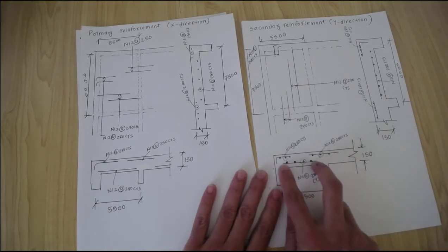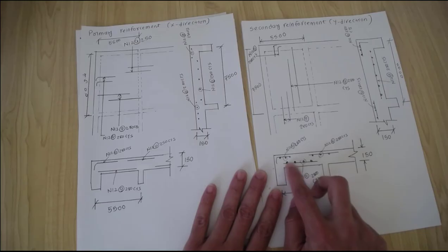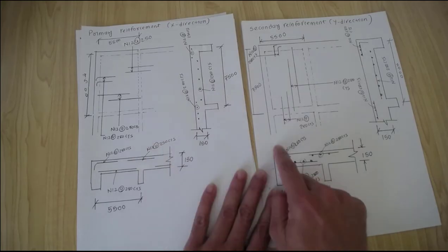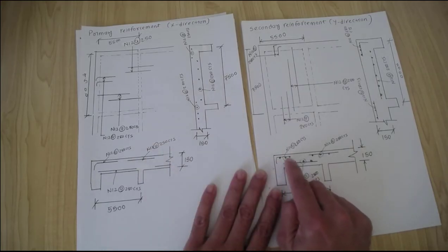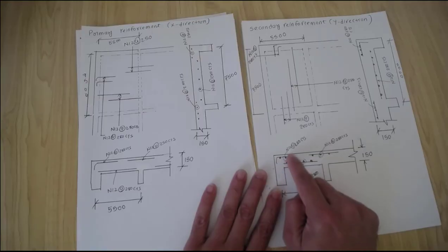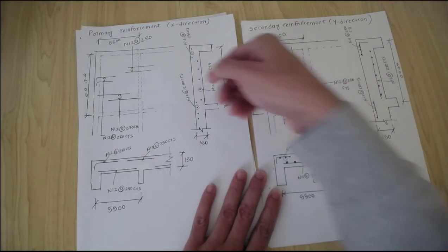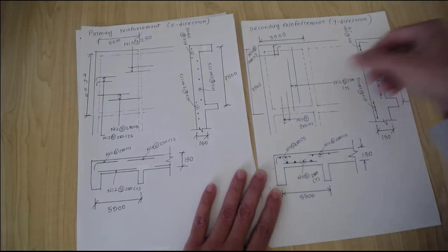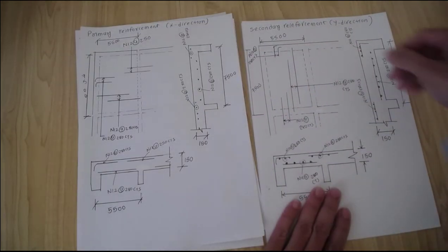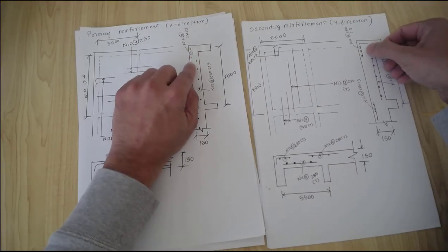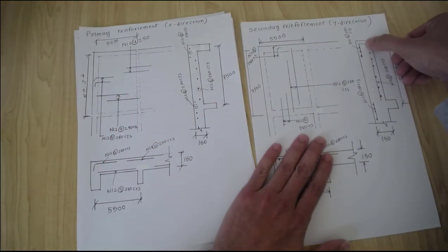Now I can draw exactly the same lines here. I draw those lines, but on top of that we draw the secondary reinforcement shown here. I draw this line and we provide this at this side. So that is secondary reinforcement at 280 center to center distance. I draw this line again and I put those reinforcement here. Similarly here, I draw the primary reinforcement, and then I draw this secondary reinforcement at the midspan. I draw again those primary reinforcement, which are these three dots. I put those three dots, and these reinforcement shown here are the secondary reinforcement.